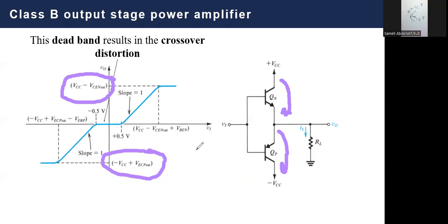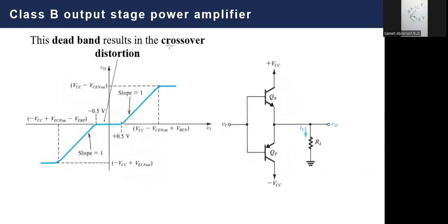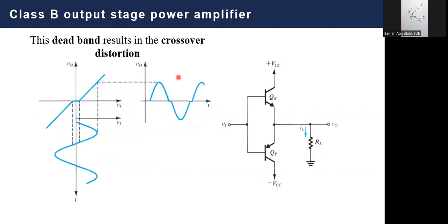So your transistors will have boundary limits related to the saturation mode, which is typically the same as in class A. But what is maybe new here is the observation of this dead band where both QN and QP are turned off. The first question that may come to your mind now is how this dead band affects our operation. You can see the answer here.